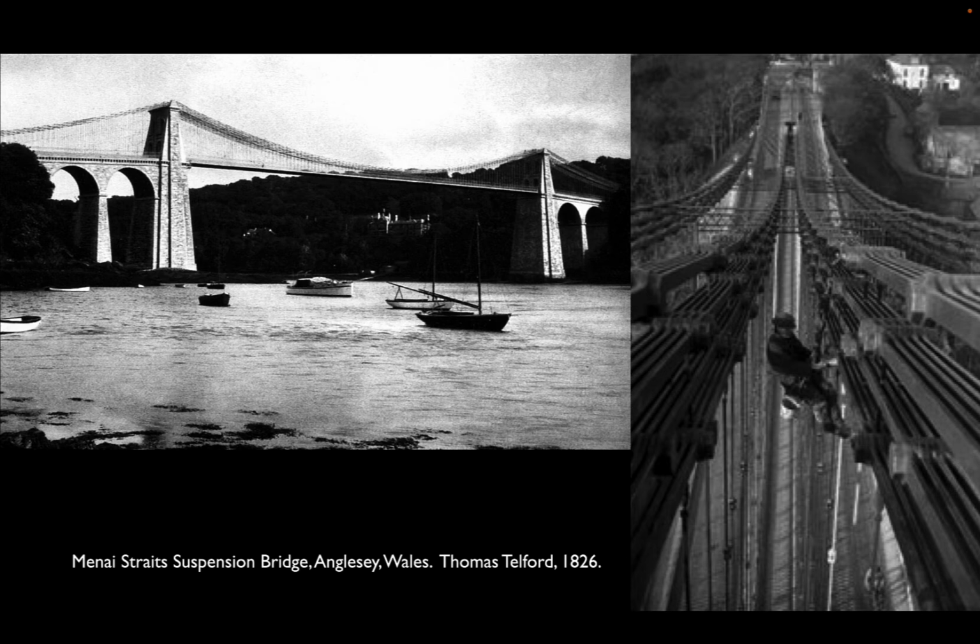And really the first large-scale versions of these was over the Menai Straits in Wales. Telford's scheme here was to build these two giant compressive structures that would lift the wrought iron chains up above the deck far enough that you would get a little bit of a catenary shape, right? Not a full catenary, but enough that the chains are always going to be in tension. The weight of the deck puts a consistent load on the chains, so they take that shape naturally.